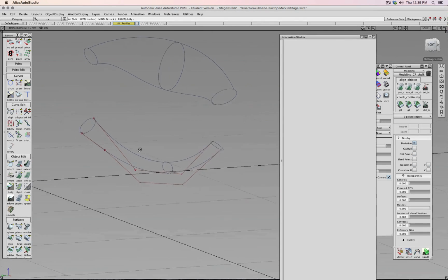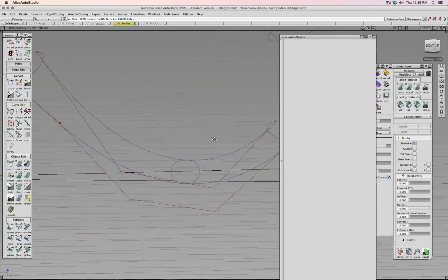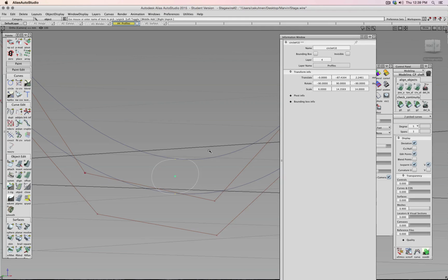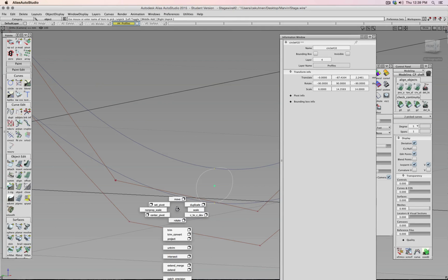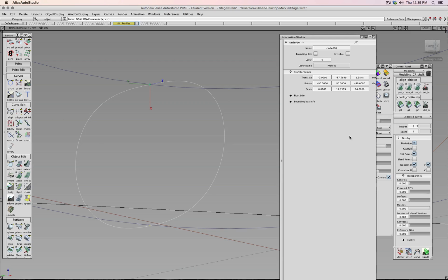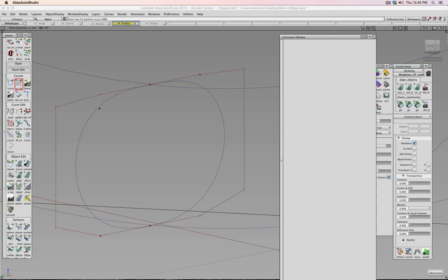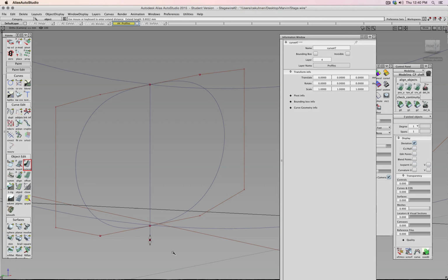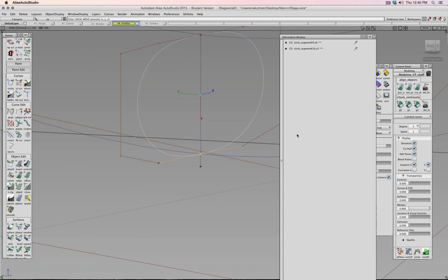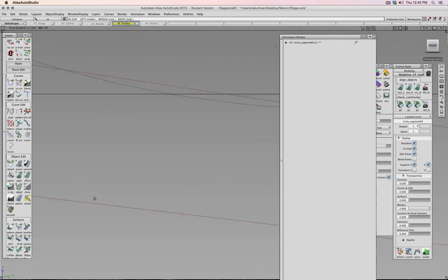Good. Let's hide this one. What I need to do now is actually make sure that this arc here in the center first sits on it and then also is correctly touching the lower part. So I'm going to adjust my pivot point here, move to there, okay, and then show me my CVs, nice, and snap, making this line, extending the line, and I'm going to CV and move along this line till it intersects, and then this point to the side view.